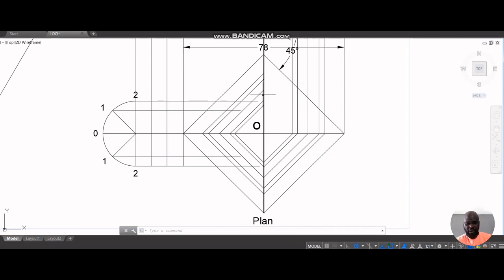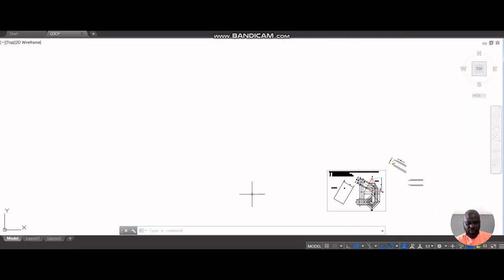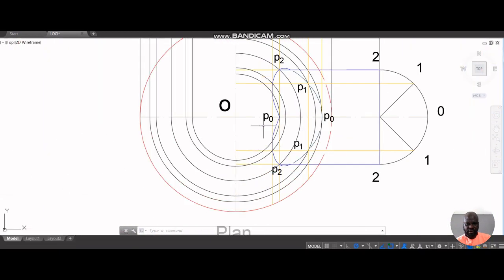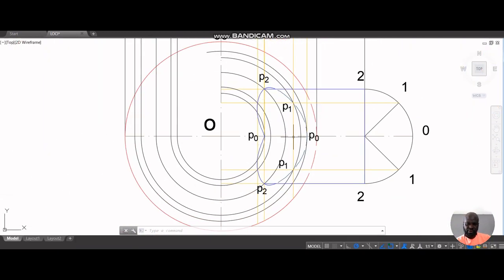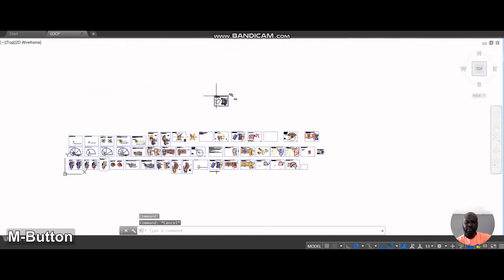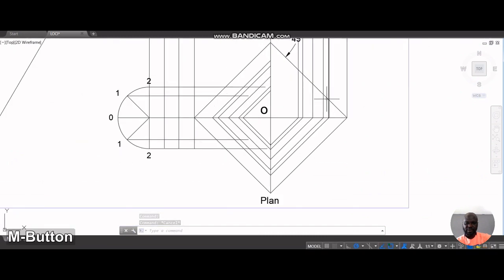You recall that this is more like what we did in the case of a cone. But in the case of a cone, let me show you quickly what we did. Because the base of a cone is circular, we had to go in circles. These are the circles, right? From this center horizontal line, we started going in circles until we cut all the cutting planes that are associated with that particular drawing. So now let's get back to the pyramid. Same thing, same action, same action.